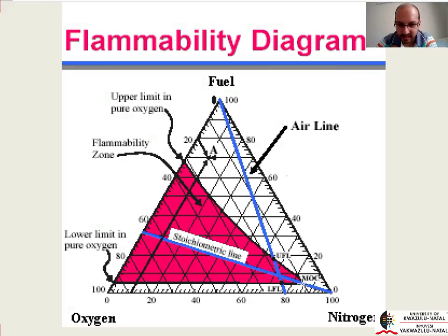Okay, so as you can see, remember you're reading your oxygen off by going up here, so that's your oxygen. If you go any lower, there'll be too little oxygen to actually burn all of that fuel and to have combustion occurring. So if you know these relevant points, you can quite accurately draw up a flammability zone and determine whether a fuel can be flammable in a variety of situations.